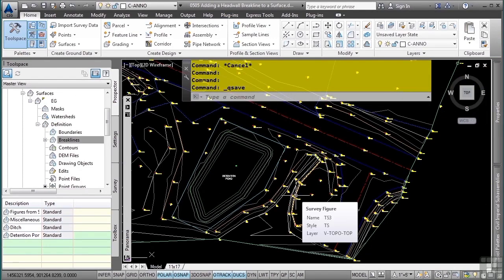Headwall break lines are useful when you only have either the top or bottom northing-easting elevation of a feature, and either a consistent elevational difference between the points, or a measured distance at each vertex. This depth would, in most cases, come from the surveyor's notes. A few examples of using the headwall type break line are curbing, as long as there's a consistent depth for all points, or a concrete culvert where the top of the culvert was located and the depth of the bottom points would be measured in the field.